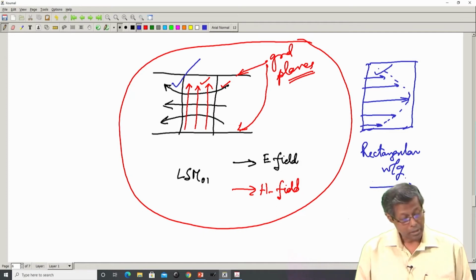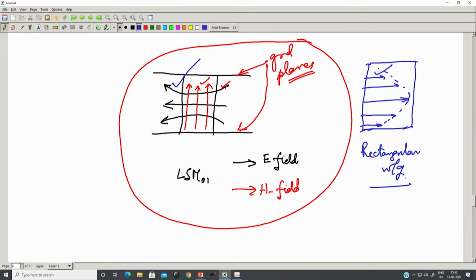As we also discussed, the low loss nature of the NRD is fundamentally due to the field profiles of its modes. Because in the LSM 01 mode field profile, the magnetic field is normal to the metallic plates, so there is a reduced electric current in the metallic plates.